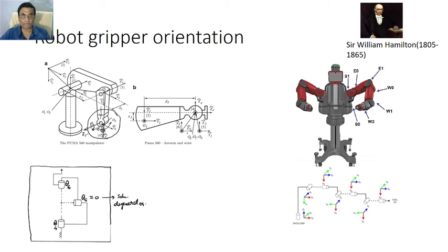So that's a problem, meaning in some situation, for example theta 5 equals 0, this is the signature of gimbal lock. This is the drawing of the gripper and this is the gripper signature, which shows that Z5 is perpendicular to Z4 and Z6, okay.